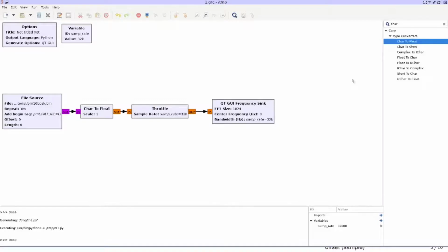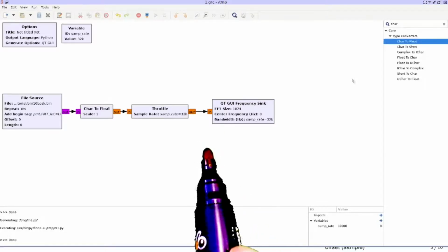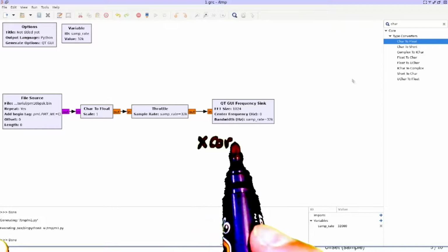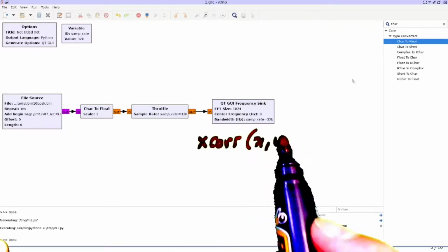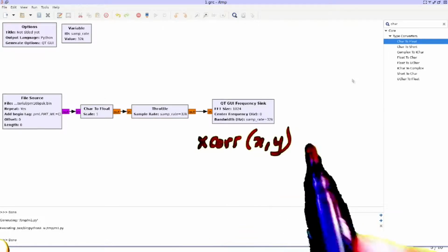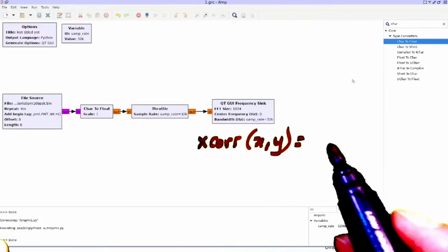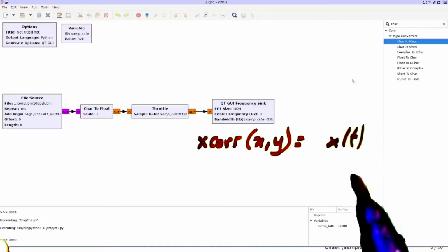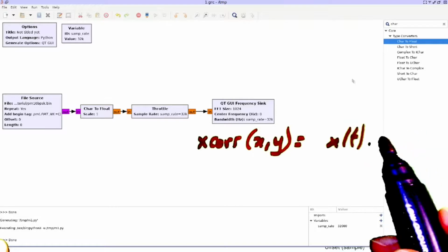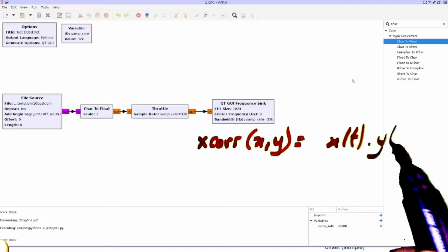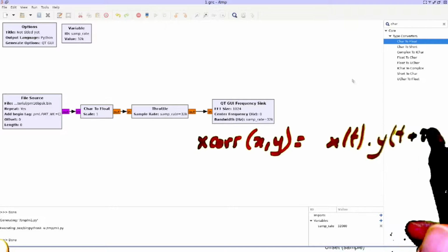And remember that the correlation is closely related to the spectral properties. So if we have a quick look at the basics of what a correlation is, if you consider the cross-correlation between two quantities x and y, we try to find a matching pattern between x and y. So we take the quantity x, which is, for example, the noisy signal that was recorded, and we try to find some time-shifted copy of the pattern shifted by a delay tau.